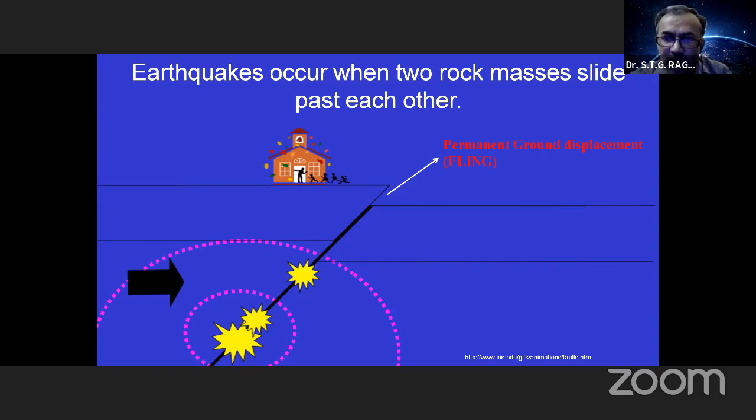So now the whole thing about earthquakes, the most important thing is this rupture speed. If things were moving very slowly, say 1 meter per second, or very slow, then no need to worry about earthquakes at all, because you will not have any vibration, and it would have been fine. So the whole thing becomes dangerous only due to the speed. So speed kills, in earthquakes also. So this is how the waves propagate, and then the ground starts vibrating. So please all of you note down this most important thing, this fling, that is what we call permanent ground residual displacement at the end of this earthquake.